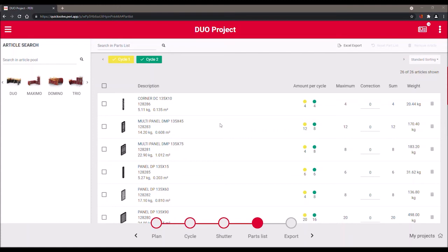One thing to note is that the wind bracing is calculated using the European DIN standards. To convert it to the minimum Canadian standards, multiply the wind bracing equipment by 1.2, so a 20% increase. And if you're in a high wind area, it's best to reach out to the engineering team and have them design it and calculate the proper wind bracing.